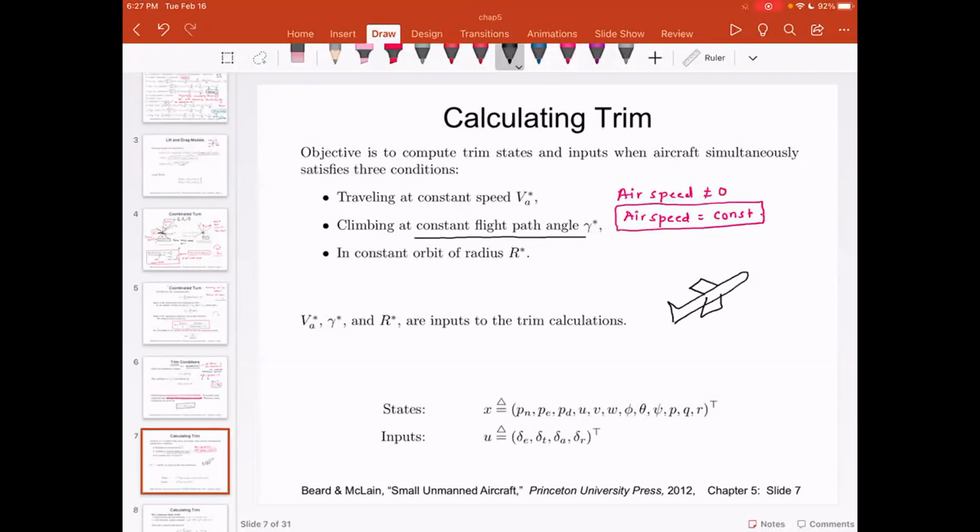You have an aircraft that is pitching, and if you look at the ground path, the ground velocity Vg, and the horizontal component of the ground speed vector, this angle is nothing but the flight path angle.